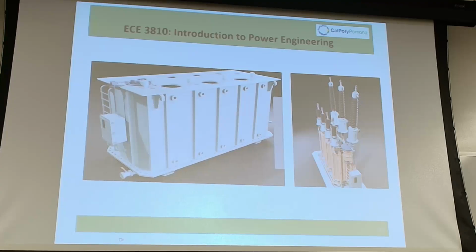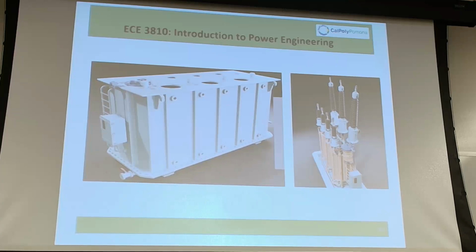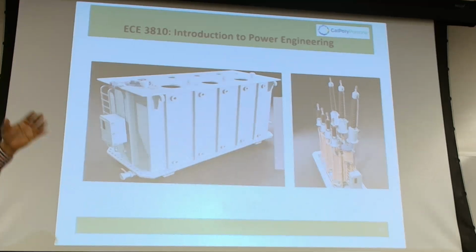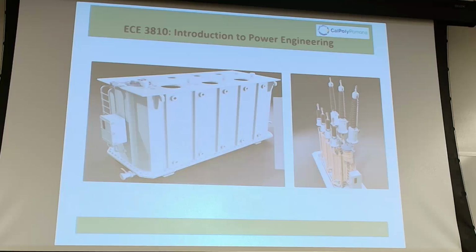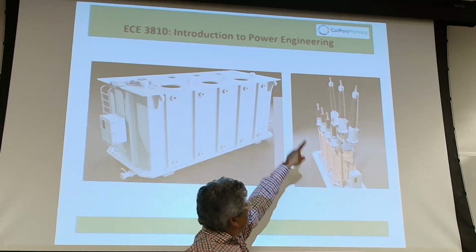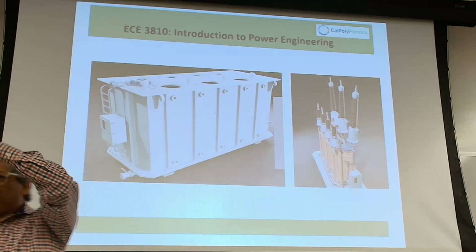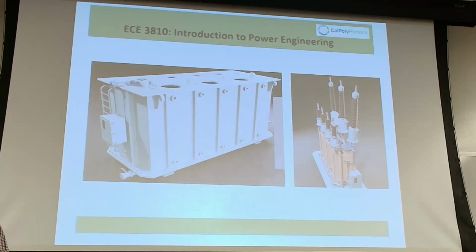There's a little window right there where they monitor the level of the oil on the insulator itself. The oil is not where the conductor goes, because that's where you put the conductor coming from the transmission line or the distribution line, and that goes into the winding, right? Inside that insulator is not just a conductor. In some cases they use something like this, like if I take this paper, it's like copper sheets, right?